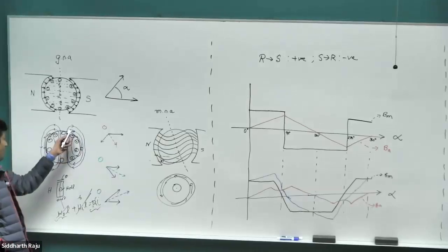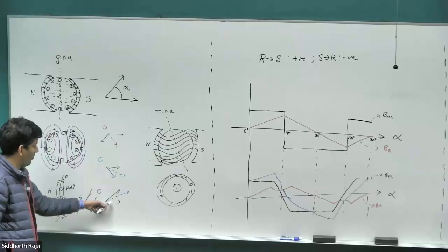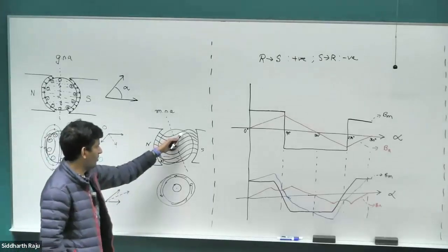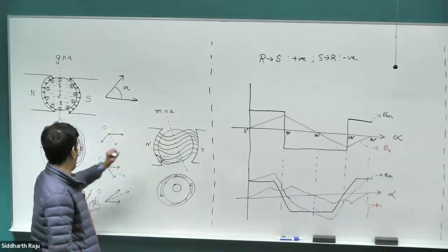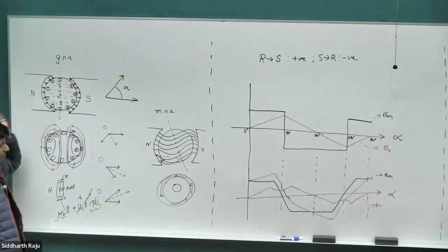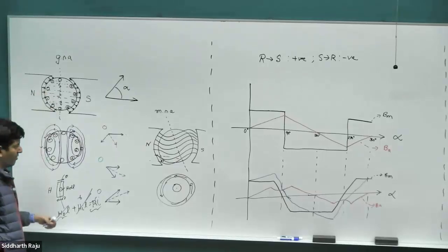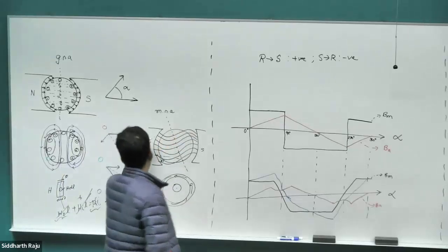And you can do this again for this spot. You have a magnetic field due to the current carrying conductor going in the upward direction, and due to the magnet in this direction, so that it ends up pulling it a little bit upwards on the top, right? So this is what the effective magnetic field would look like when you have a current flowing in the rotor. In addition to the external magnetic field that's created, there is a magnetic field due to the armature winding, and the net magnetic field is going to look like this, all right? So this is the sum of it.